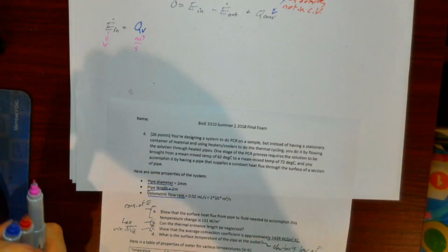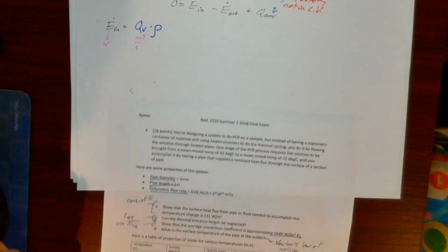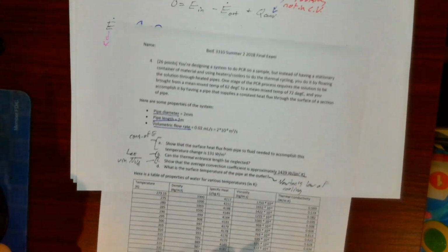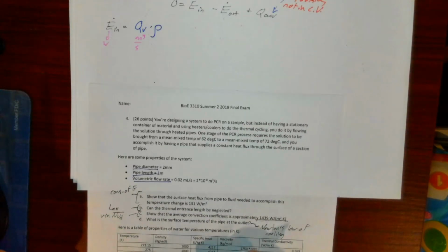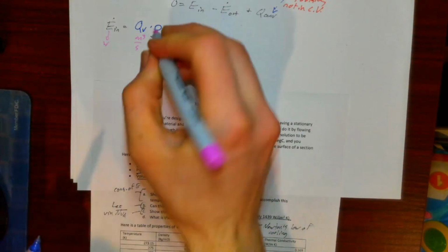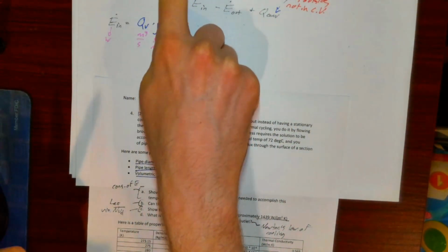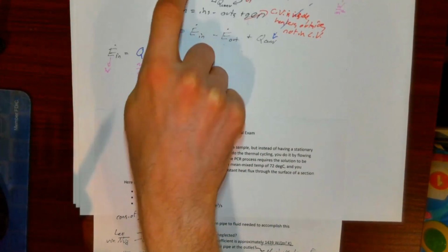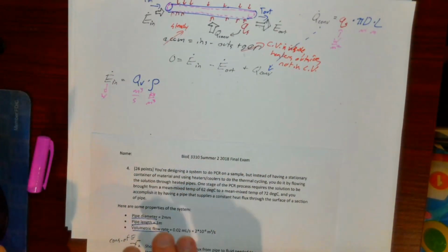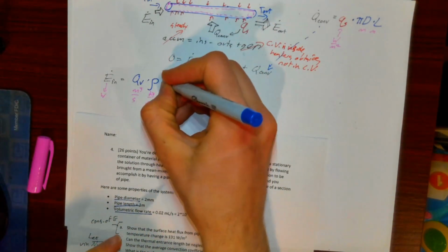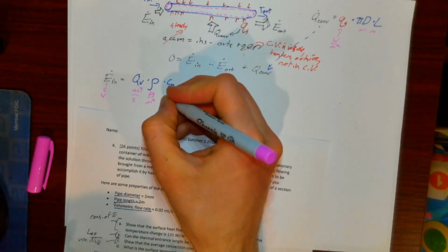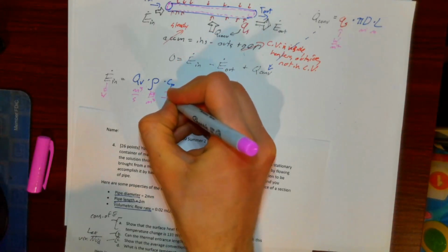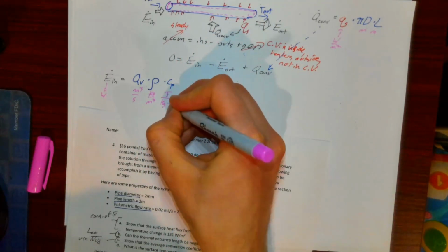And then if I take that volumetric flow rate and multiply it by the fluid density, we'll sort out density in just a second, but I'll be able to read it off this chart, so we can treat it as a known constant for now. That's going to be kilograms per cubic meter, right? So basically, the more mass that's flowing in through this inlet surface, the more thermal energy is carried by mass in. And then I could also multiply this by the specific heat of the fluid, which is essentially for every kilogram of fluid and every degree C you raise it, how much energy does it store? So that's basically going to be joules per kilogram Kelvin.